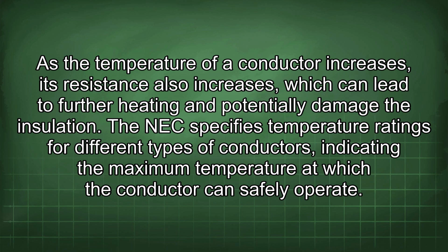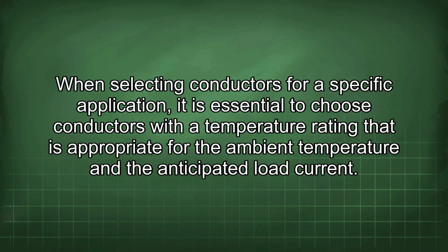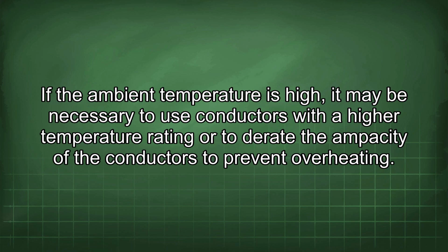The NEC specifies temperature ratings for different types of conductors, indicating the maximum temperature at which the conductor can safely operate. When selecting conductors for a specific application, it is essential to choose conductors with a temperature rating that is appropriate for the ambient temperature and the anticipated load current. If the ambient temperature is high, it may be necessary to use conductors with a higher temperature rating or to derate the ampacity of the conductors to prevent overheating.